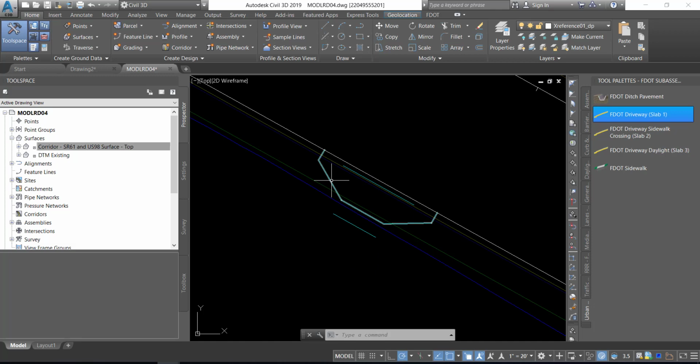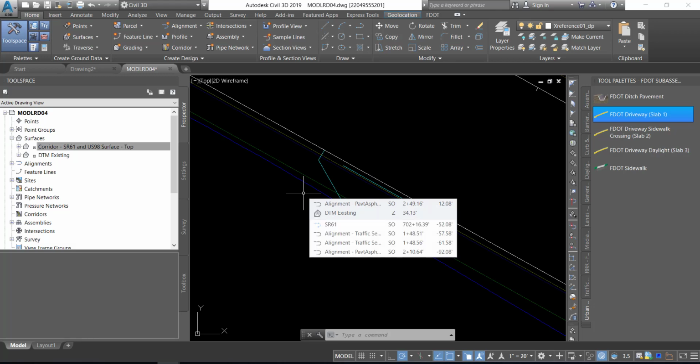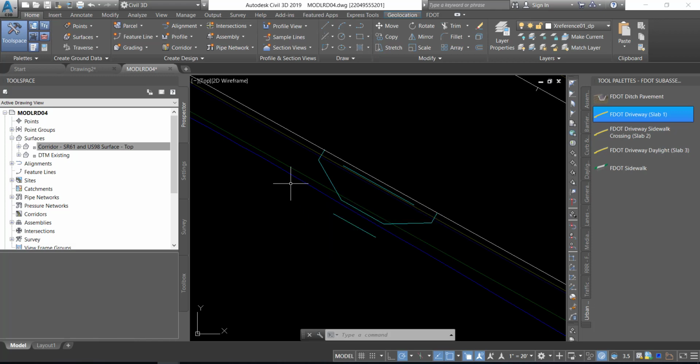Duplicate names are not allowed when naming your feature lines. The next counter follows the order in which you selected the objects. Group objects for a specific driveway are in the same site, such as Site 1. Design elevations are assigned to each vertex from the reference corridor and model surface. Finally, save your file before continuing.